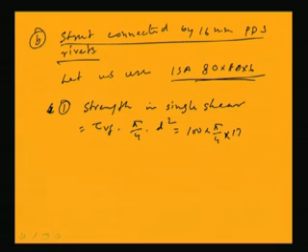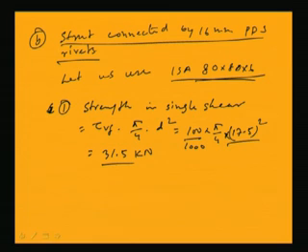D will become 17.5 because 16 millimeter power driven shop rivets are used. So, 17.5 millimeter will be the gross diameter of the rivet. So, if I divide by 1000 to make kilonewton, we can find the value, that is coming 31.5 kilonewton.